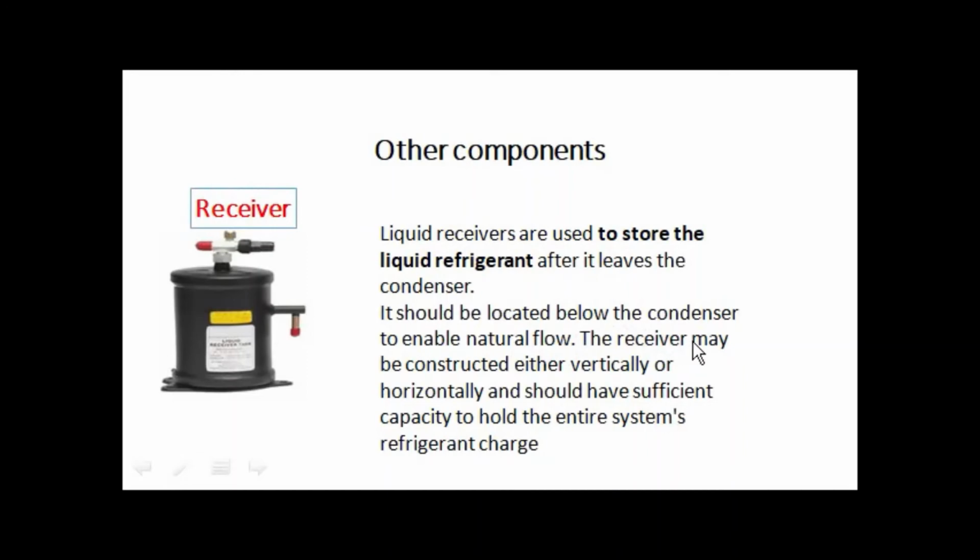The receiver may be constructed either vertically or horizontally and should have sufficient capacity to hold the entire system's refrigerant charge. This is the receiver, as you see here.